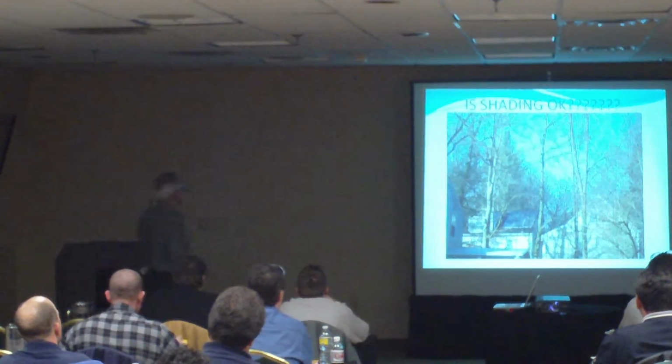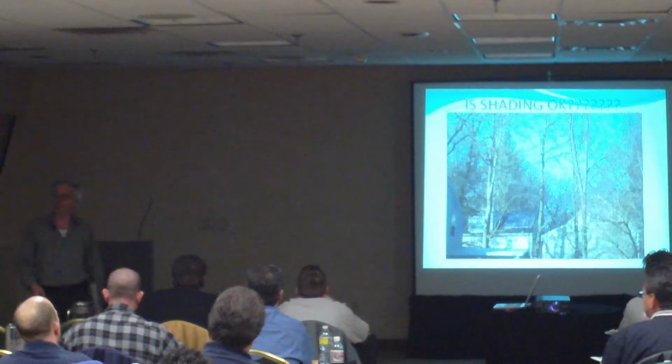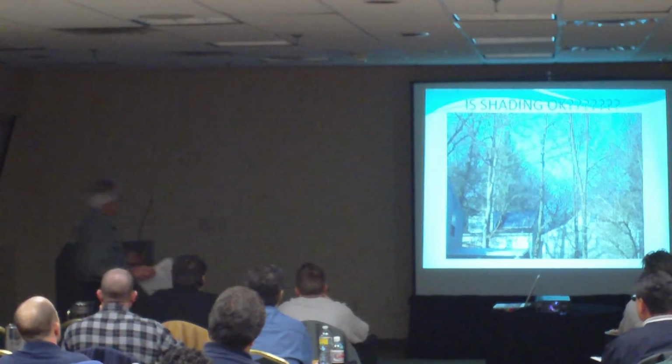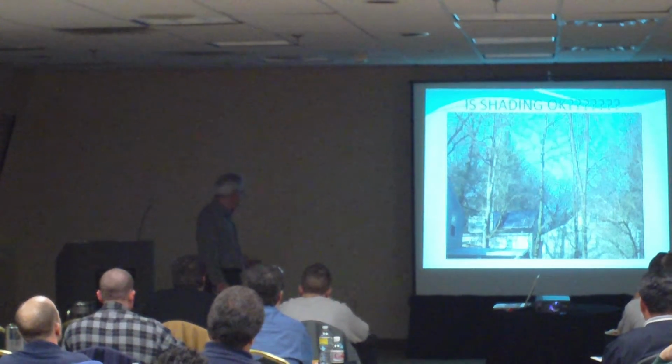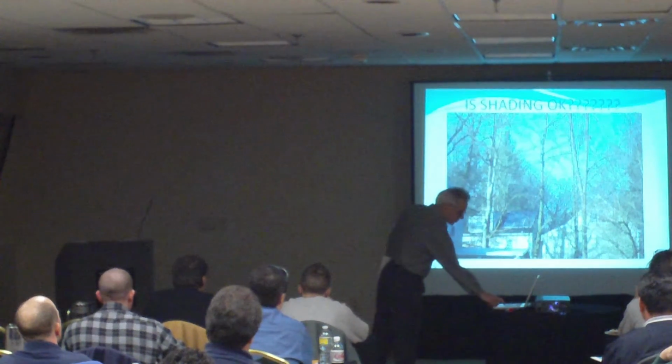But you don't know. You have 6 panels in here. 6 panels is equivalent to what? An average of 150 watts each will give you what? 900 watts. And an average 900 watts will be equivalent for whatever application this particular individual had in there. But obviously we have a problem here with shading.